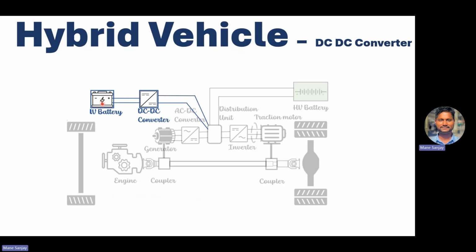Now, what is the role of this battery? When you enter the vehicle and put it into ignition mode, before putting it into crank mode, all ECUs, this DC-DC converter, BMS, hybrid controller, EMS, traction controller, or any ECUs in the vehicle need power. They need 12 volt power, and sometimes some sensors need 5 volt power. That power is provided by this LV battery, because until you are in full operational mode, you cannot use your high voltage battery.